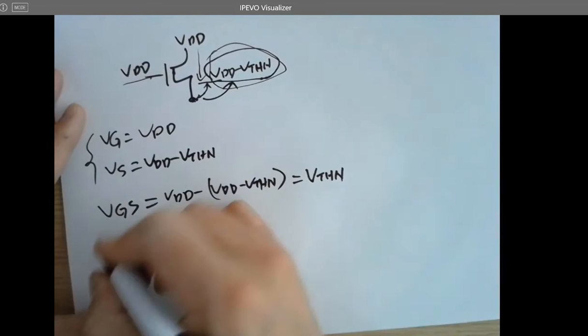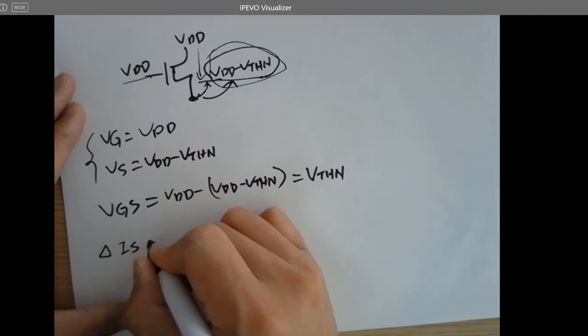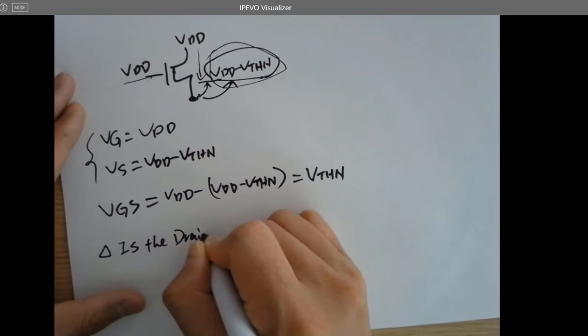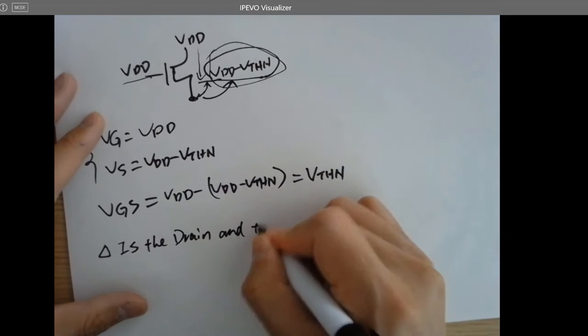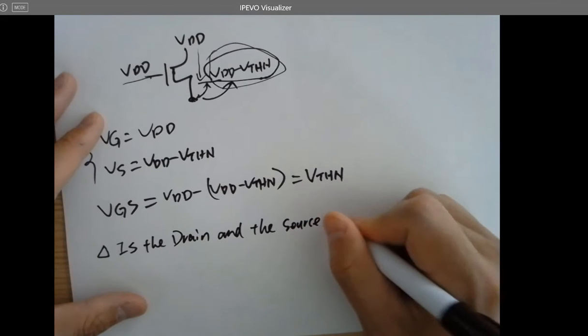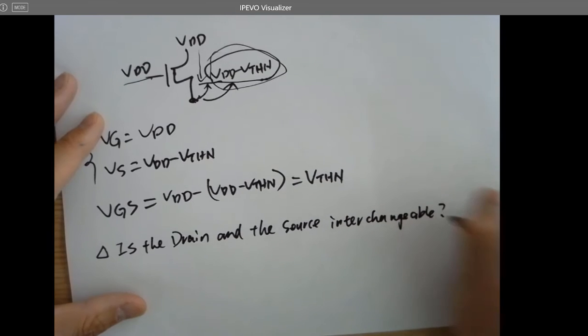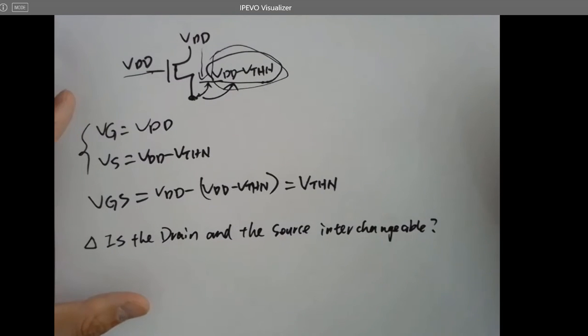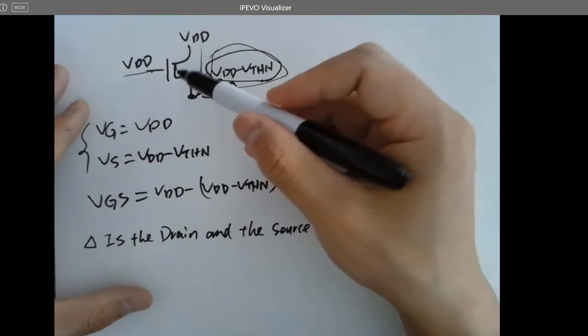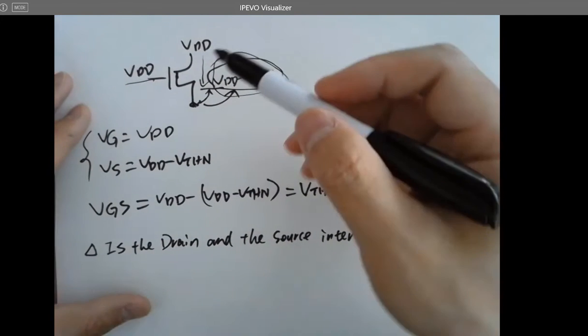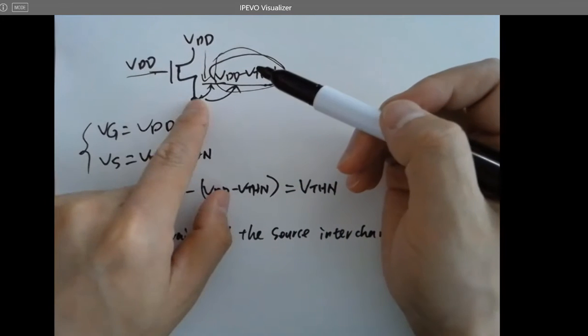So one more question. Are the drain and the source interchangeable? Just in your CMOS C5 technology, in your Electric VLSI, are you seeing any difference? There's no difference, right? When you are doing the layout, can you already tell the difference between drain and source? No. So why, if we connect the transistor in this way, are we saying that this is source and this is drain?